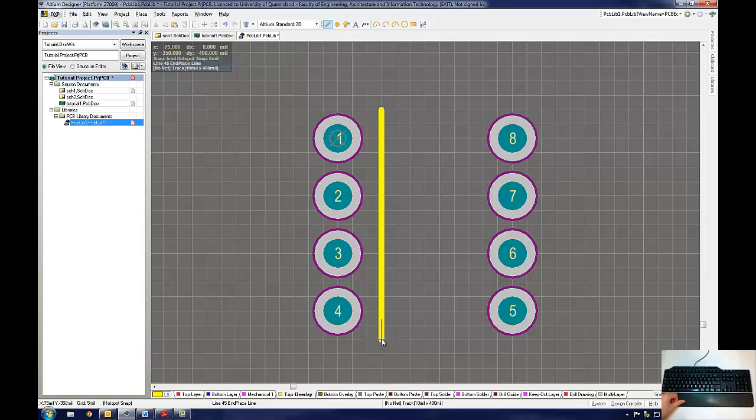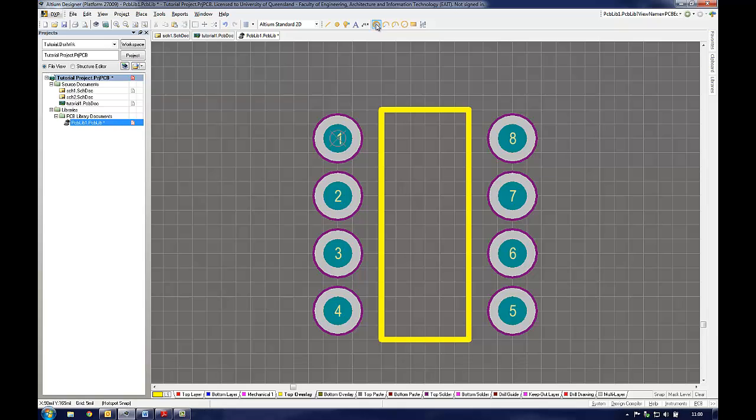Another set of tools are the Place Arc By tools. These allow the user to place perfect curves on the component outline, which is particularly important for electrolytic capacitor bodies. These tools can also be used to place dot markers on pin 1 of ICs as well as IC notches for correct orientation of chips. The user can also place descriptive text, dimensions, and solid polygons on the component body if required.